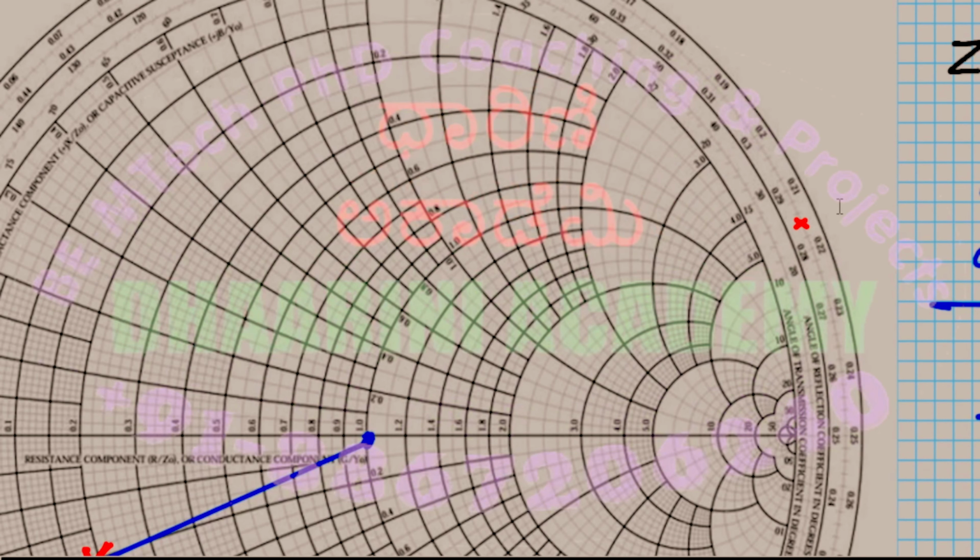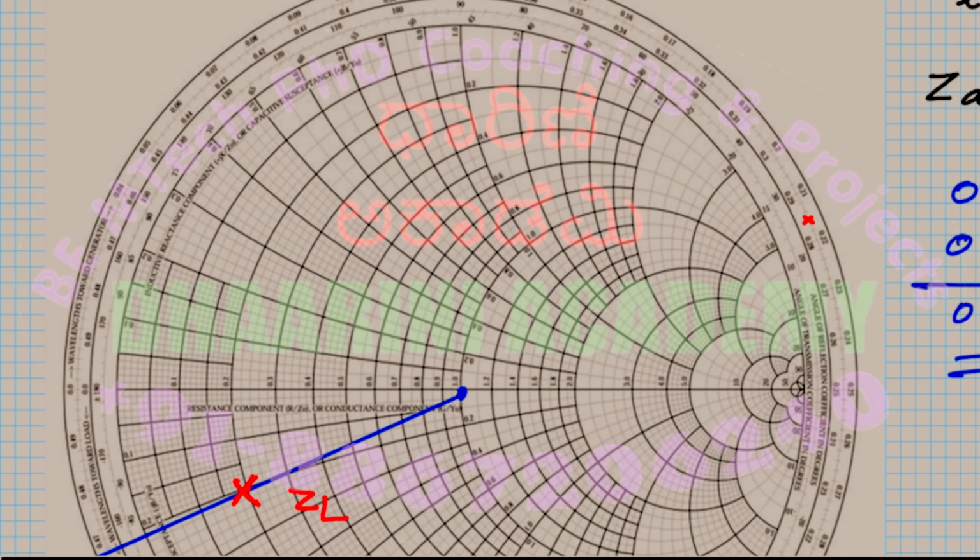Is it okay? So I got a 0.216 and I am supposed to connect that point to the center. That's all. So let us connect. From the center, draw a line that actually passes through that. Mostly this becomes a proper straight line from the beginning, right? So I'll just write this point is 0.216 lambda.